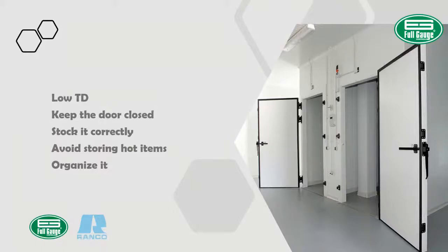Some of those conditions are a large evaporator surface. A fully active evaporator will also help to maintain a low temperature difference. Also rapid and fast air circulation, and a frost-free surface. These conditions will promote slow frost buildup, high suction pressure, high capacity, and efficiency.